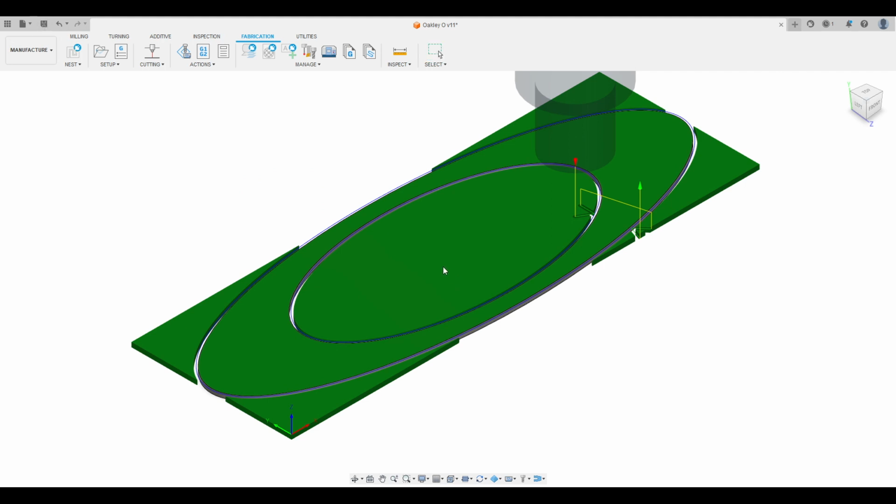From here, we're going to save before we move on. And we're going to come up to our post process. Now, post processing is going to allow us to export our code somewhere else. Under post, I'm simply going to hit the folder icon. And up top in your search, I'm going to type Hypertherm Jet and hit select. It's going to ask us to copy our post process into our library. So what I'm going to do is hit choose another location, or I'm going to hit local. If this does not show up, just choose another location and click local and hit select. Copy.